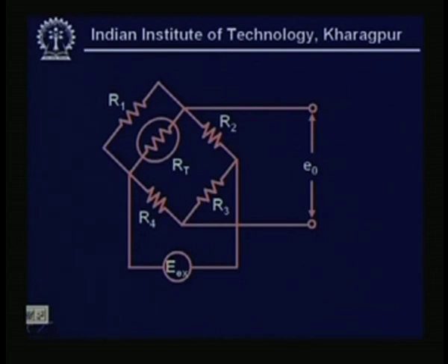there is a typical reason why we have connected a resistance in parallel with the thermistor. Now, as I told you, thermistors are nonlinear devices. So, linearity is a great problem with the thermistor. So, what they do, this is a common rule of thumb, is to use a resistance in parallel with the thermistor, right. So, what will happen, you see,